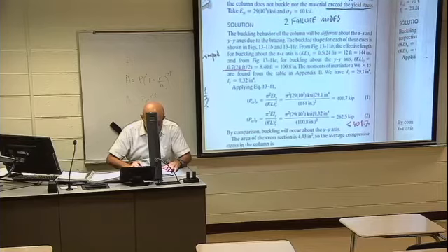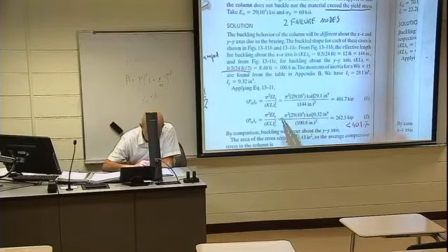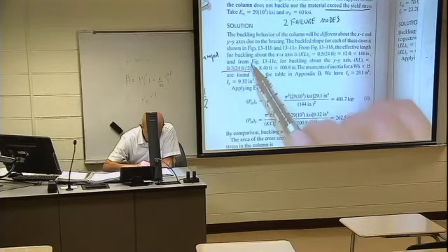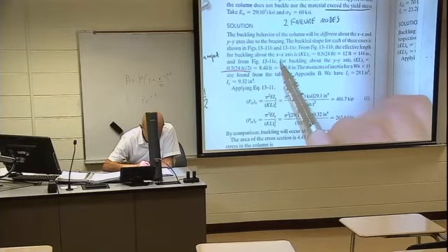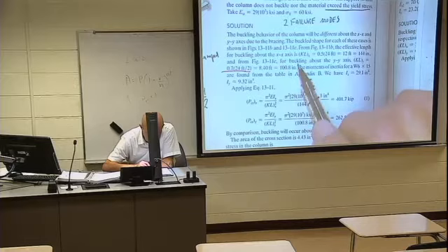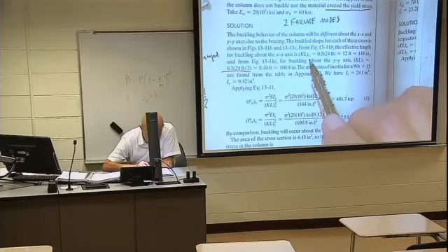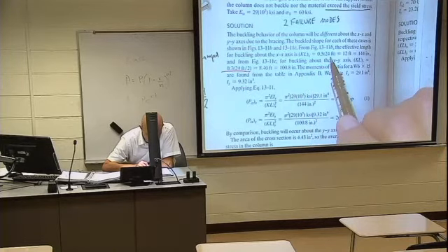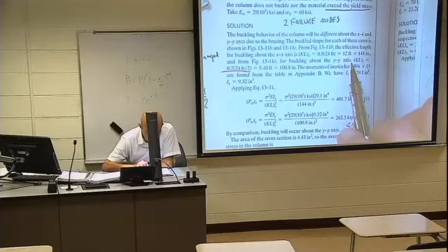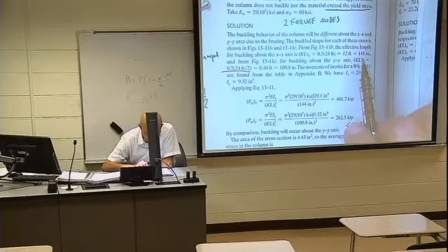So let us come back. The effective length for the buckling about the x-axis is KL in the x direction, because half of 24 feet will be 12 feet, and that equals 144 inches, because a foot contains 12 inches.